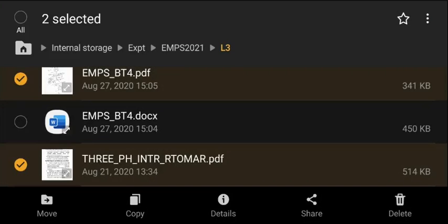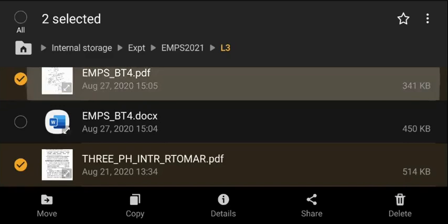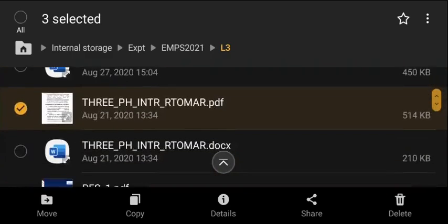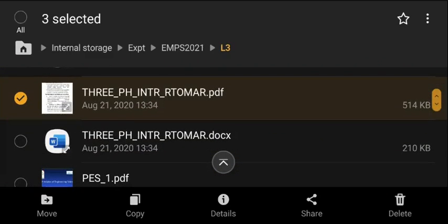Three independent voltage generators with 120-degree progressive phase shift between them. One generator with 0-degree phase shift, the next one with minus 120-degree phase shift, and the third one with minus 240-degree phase shift, and connected in a certain manner. That's a three-phase system.